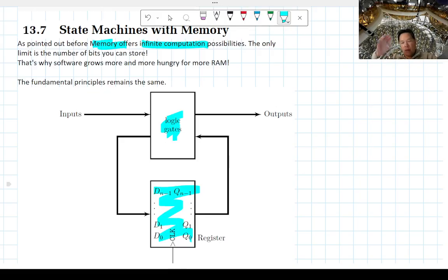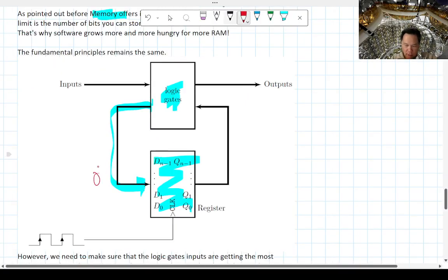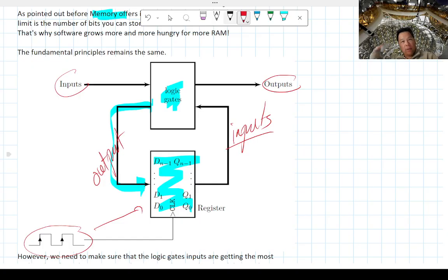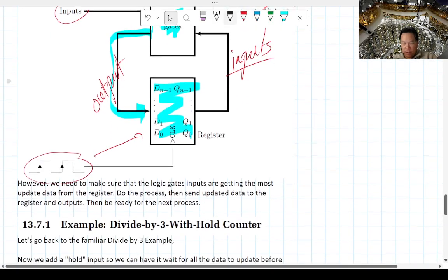Okay. So you have an output from these logic gates that can go to the registers. And then the registers can be read out as inputs also, because maybe you want to read out the previous calculation you did, so you can do it iteratively. And then eventually you have an input and output that controls everything. And this is, of course, the sequential part, which requires this clock to be going up and down to tell the register how to sync up.